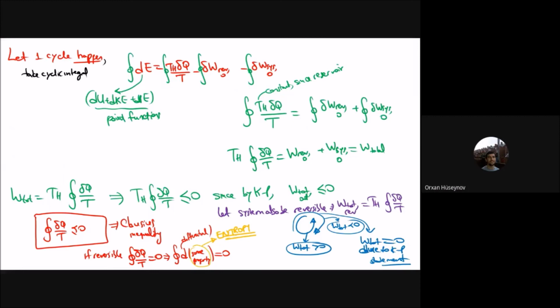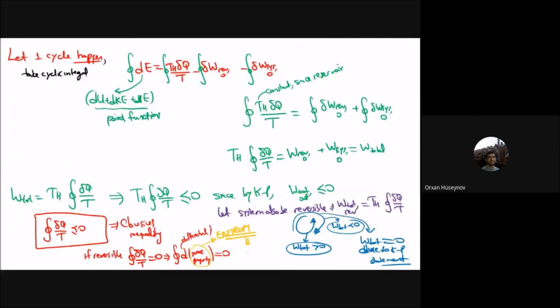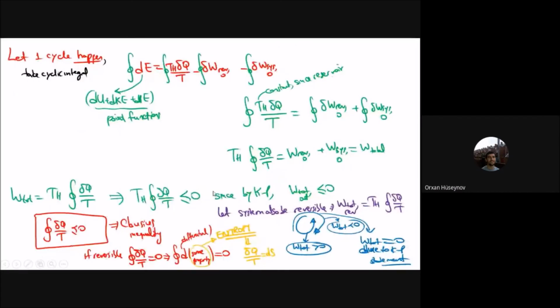And so the name is entropy. Okay, this is the entropy, and by using these relations here. Therefore, entropy is that del Q by T, and that is ds. Okay, with this one, I finish the introduction to entropy, and in the next lectures, I will use this final relationship here and derive the important relations for the entropy changes of pure substance.